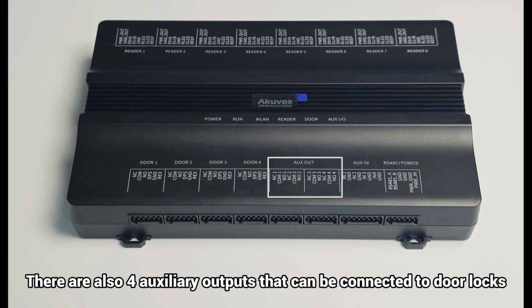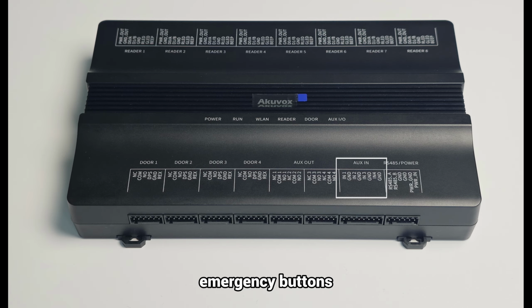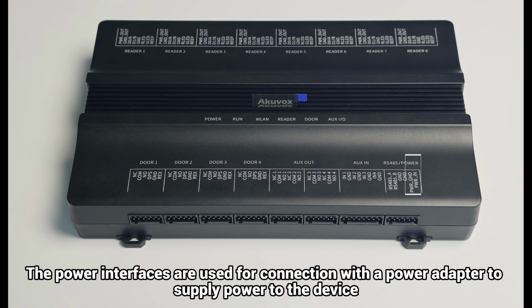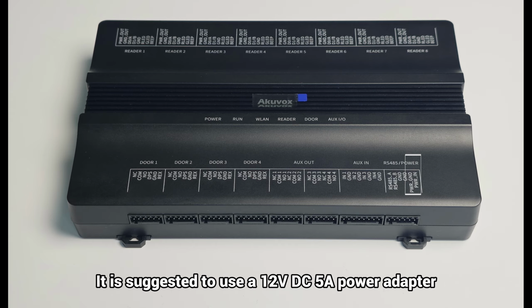There are also 4 auxiliary outputs that can be connected to door locks, and 4 auxiliary inputs that can connect to push exit buttons, emergency buttons, door sensors, etc. The RS-485 interface allows for connecting to the elevator control device. The power interfaces are used for connection with a power adapter to supply power to the device. If PoE Plus is not available, it is suggested to use a 12-volt DC 5-ampere power adapter.